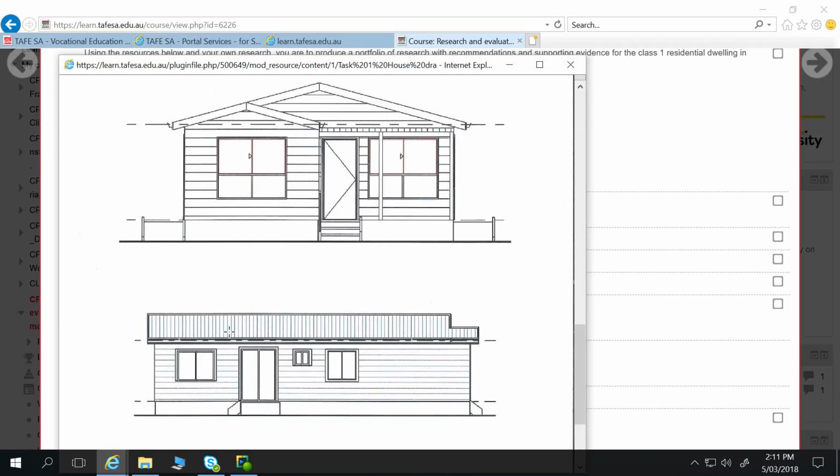So that's our shed here, and we've got typically vertical sheeting on that. And let's say it's a gable end like that. The reason we have typical vertical sheeting on that is because we have our wall girts which run sideways between our portal frames. But if we were to slice straight through that shed, looking in the same fashion, we would see that we have